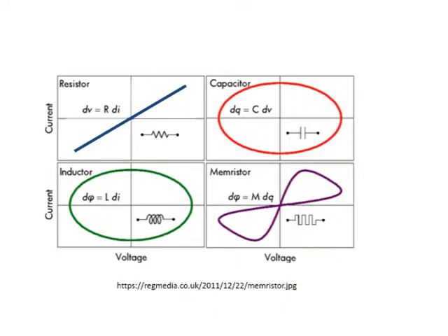A capacitor stores energy in the form of charge differences between conducting plates. When voltage is removed, that energy is released, meaning that current continues to flow at zero applied voltage. The inductor stores energy in its magnetic field as voltage is applied. It too has current flow energy, even at zero applied voltage. The memristor, like a resistor, stores no energy. When the applied voltage goes to zero, no current flows. What makes a memristor different from a resistor is the pinched hysteresis loop, where the resistance changes in a stable way depending on how much current has flowed through the device.